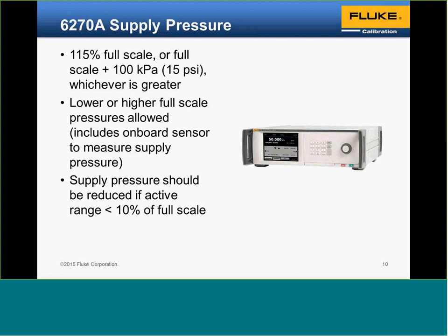Now, it's like the PPC4: supply pressure must be greater than the highest pressure that you want to go to. Others do not have a built-in pump or compressor or anything where they can generate pressures higher than what's given to them. There's some metering in the pressure that's given. They need to provide a supply pressure greater than the pressure that you're looking to go to.